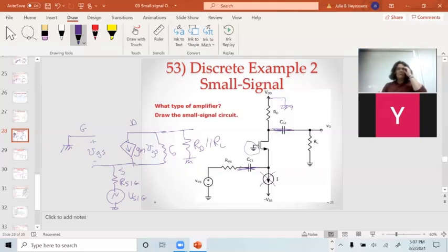Once you're able to draw those circuits, you can either do the circuit analysis by hand, which is some people's lazy way, or you can do it my lazy way: if I look at it and I'm stumped, I plug this model into Multisim, figure out what I wanted to know, and then check it against reality. If I get a huge gain through a common gate amplifier, I'm going to be surprised and fix my circuit.